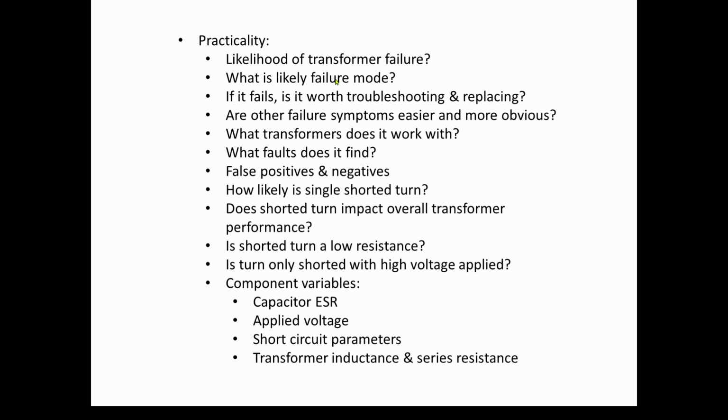So for example, a high voltage spike, if the protective equipment doesn't protect the transformer, what's going to happen? Well, it's probably going to flash over. The insulation is going to fail, and you might have either a temporary or a permanent short circuit. Is this tester going to help you with that? Right? So you have to think about what's the failure mode. And is this tester designed to detect that failure mode?